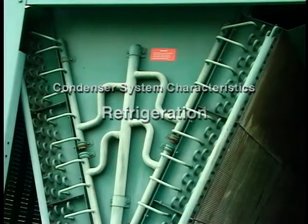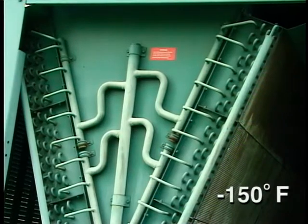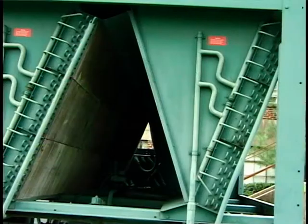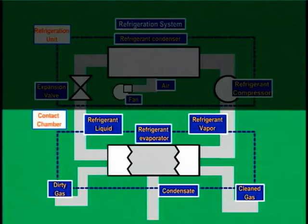Refrigeration systems use compressed coolants and operate at temperatures as low as minus 150 degrees Fahrenheit. The most common coolants use CFCs, although this is changing in response to the Clean Air Act amendments of 1990. The refrigerated liquid, flowing through tubes in a shell and tube heat exchanger, absorbs heat from the gas stream flowing on the shell side, reducing the gas stream temperature and causing the contaminant to condense.